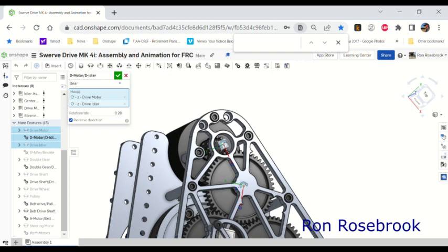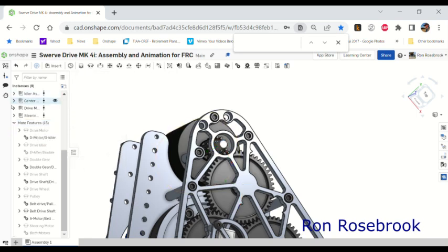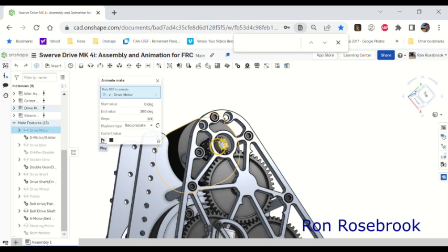After you enter that relationship, test to see if the gears are meshing correctly. You run the test by animating one of the revolutes. Okay, in this case, you can see that the teeth are clashing.